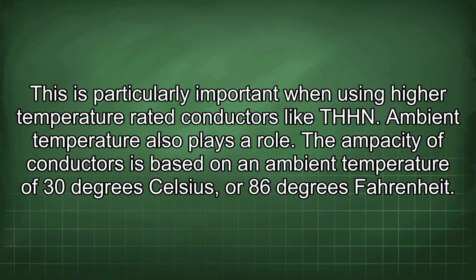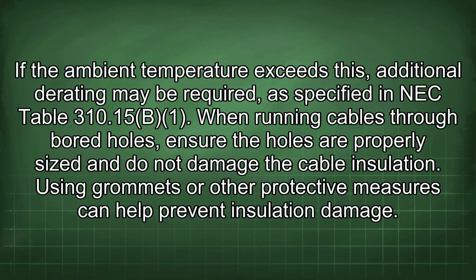Ambient temperature also plays a role. The ampacity of conductors is based on an ambient temperature of 30 degrees Celsius or 86 degrees Fahrenheit. If the ambient temperature exceeds this, additional derating may be required, as specified in NEC Table 310.15(B)(1).